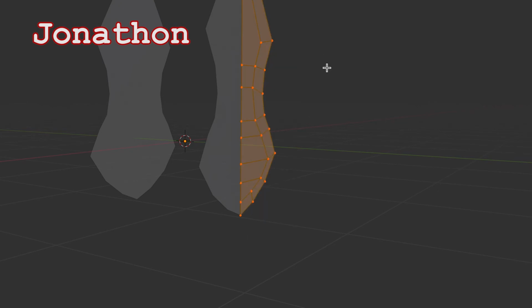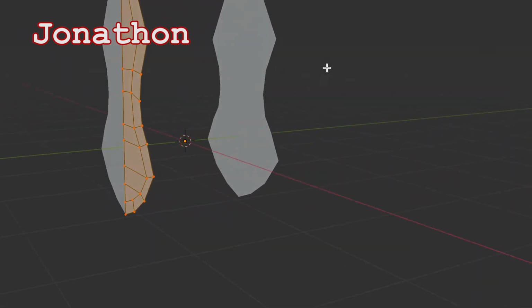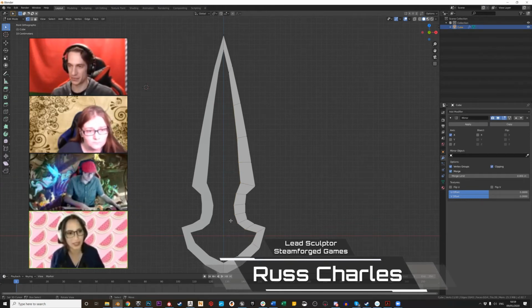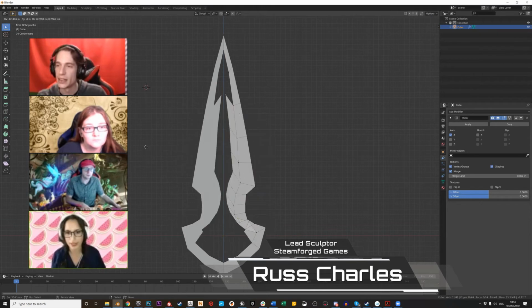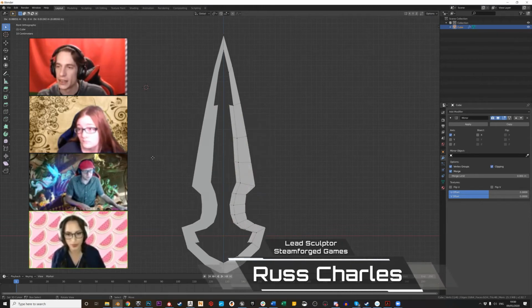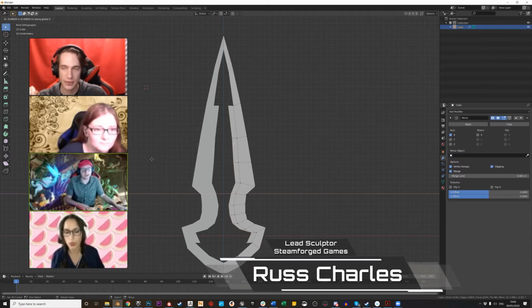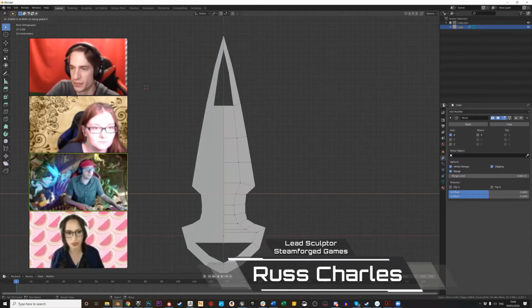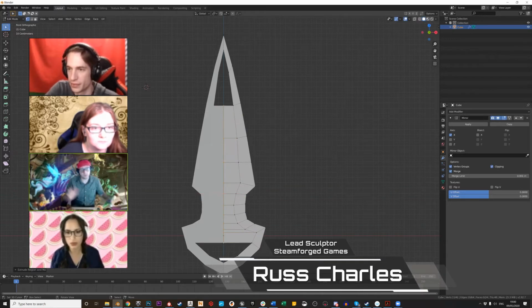I'm at the part where I'm doing the Y mirror. So my F key is. I'll wait. Once you've selected all of those, you hit E to get the extrude function working again. Okay. And then you press X. Whenever you activate a tool, if you press X or Y or Z, you lock it to that axis. Because it's locked to X, you can only move side to side. So you just pull it all to the middle, and you should end up with it all connected apart from a hole at the bottom and a hole at the top.